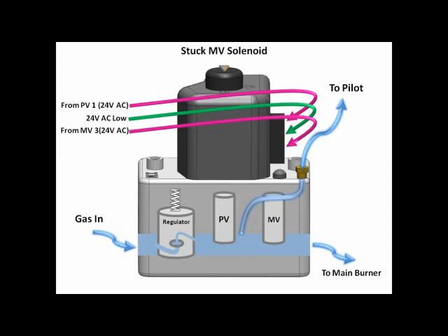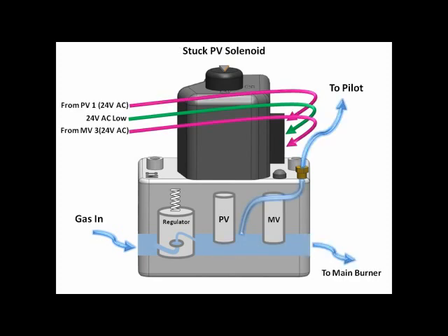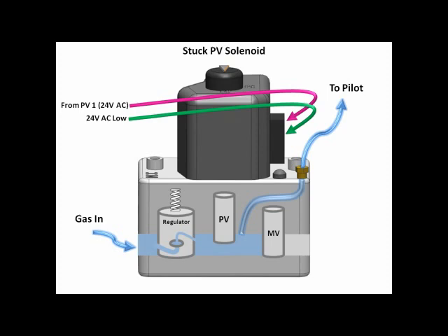It is very rare but possible for a solenoid to stick open when a valve fails. If the call for heat stops the voltage to MV but the solenoid sticks, the main burner gas does not stop. The high limit will stop the input to the module and PV voltage is ended. And when the PV valve closes, the main burner supply is stopped. In normal circumstances, when the temp control satisfies, MV voltage is disconnected, stopping the output to the main burner.